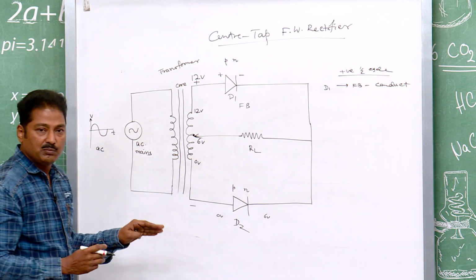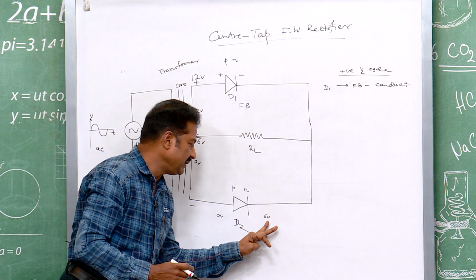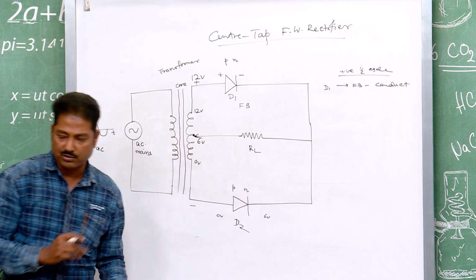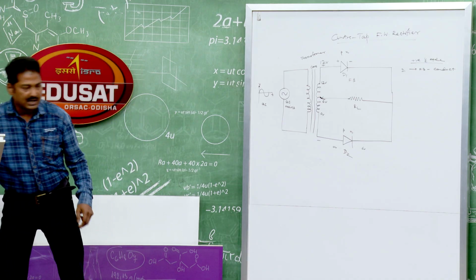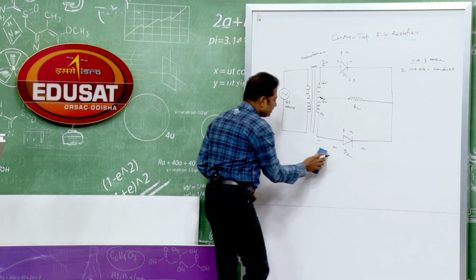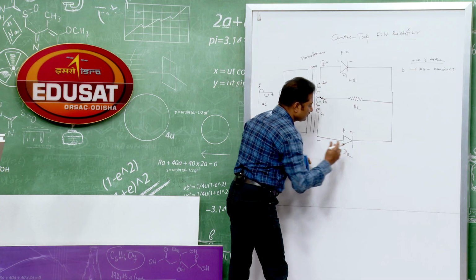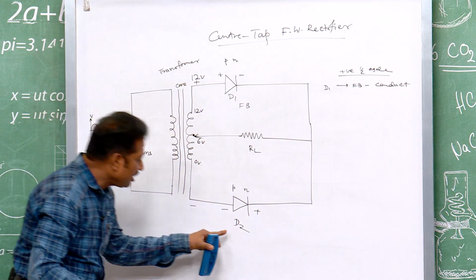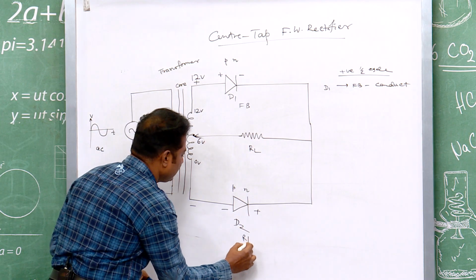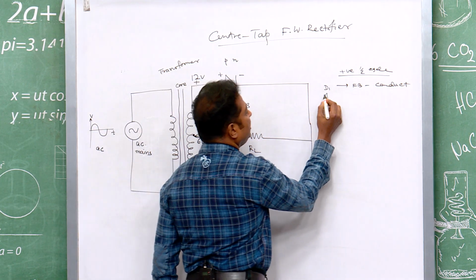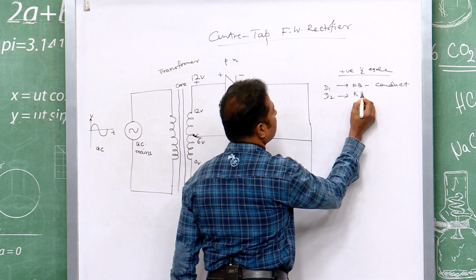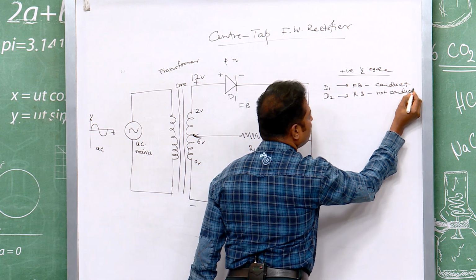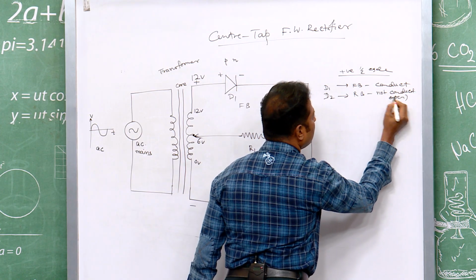Then as I mentioned, the higher potential will be taken positive and the lower potential will be taken negative. Therefore, what will we assign? We should assign the positive sign here and the negative sign here. Now, what will happen? This is reverse bias, obviously. So, D2 is reverse biased, does not conduct, an open switch.